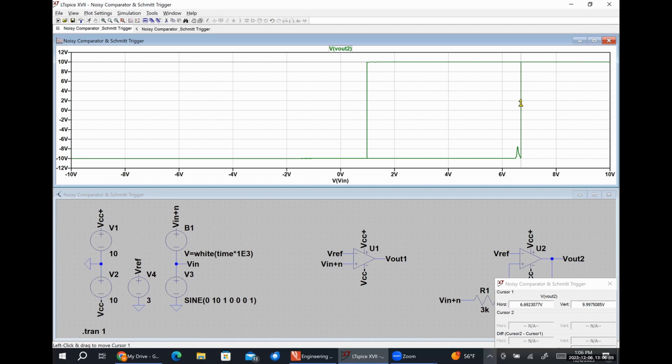So we've got a pretty good estimate of how to calculate what our lower trigger limit is and what our upper trigger limit is. And it's just based on the resistors that we choose, and also on our reference voltage. This might not be intuitively obvious, but I'm mentioning this specifically because I'm going to ask you to design one of these in one of your design projects for the class.